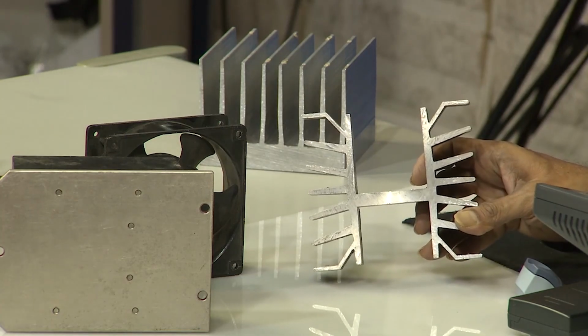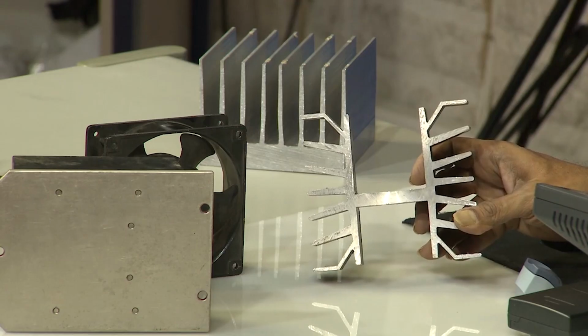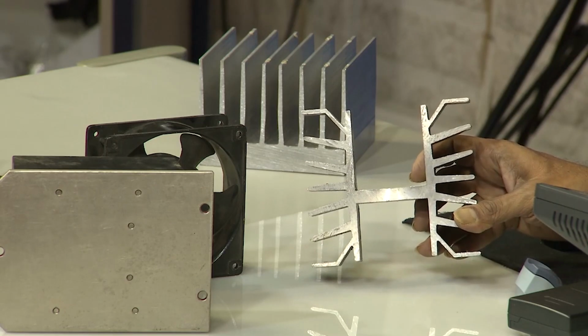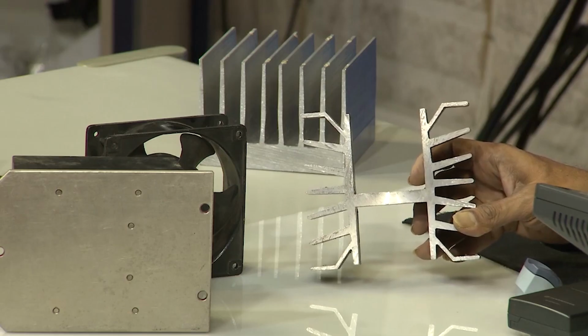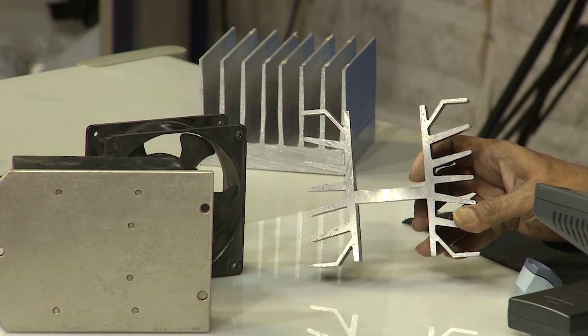You see the way the fins are tapered to improve the fin effectiveness. If you consider all the other things, I have a fan here, so why not make it deeper, and the consideration about the depth or spacing, you have only so much control, not infinite control, as you would have for an analytical thing.